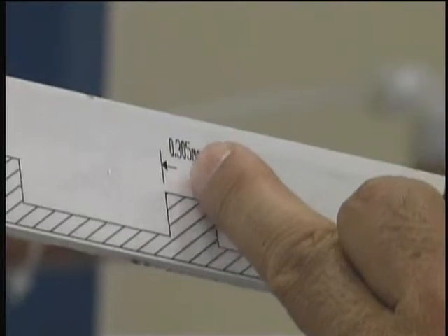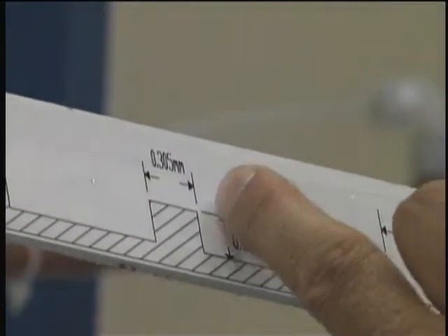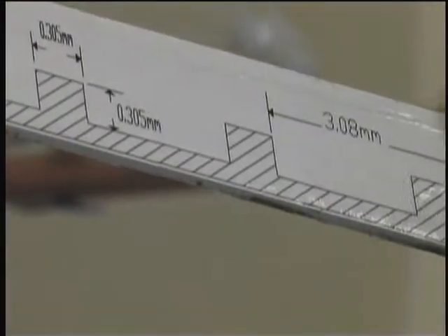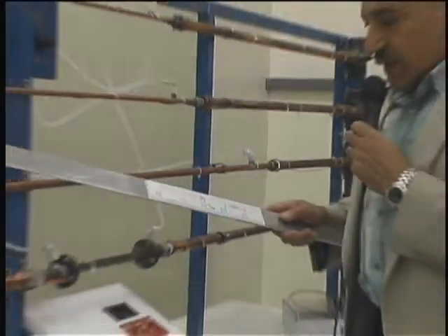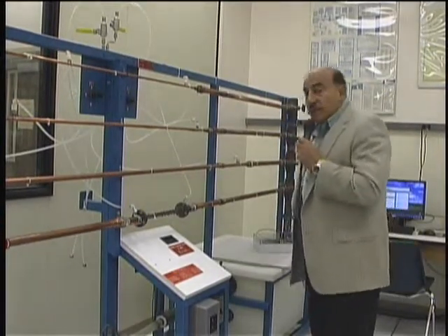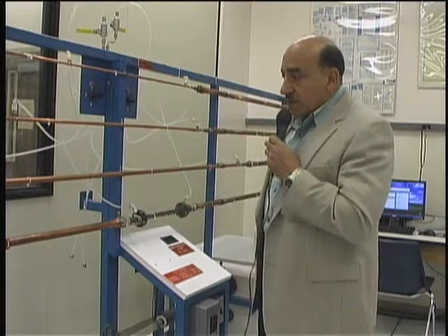So you have here, this is 0.3 millimeter wide, and the height of this protrusion is 0.3 millimeter. And then the distance between, or the pitch, is 3.08 millimeter. So with this type of structure, we have a correlation from which we can determine the effective sand grain roughness for that particular pipe